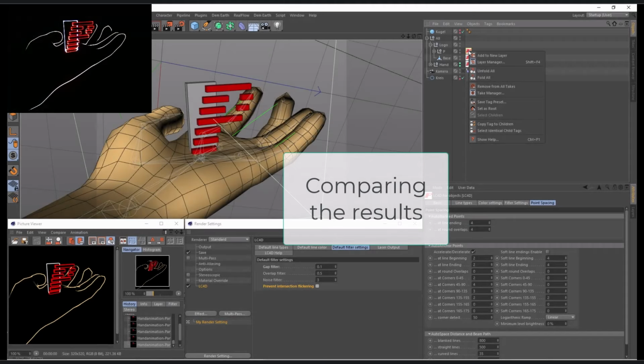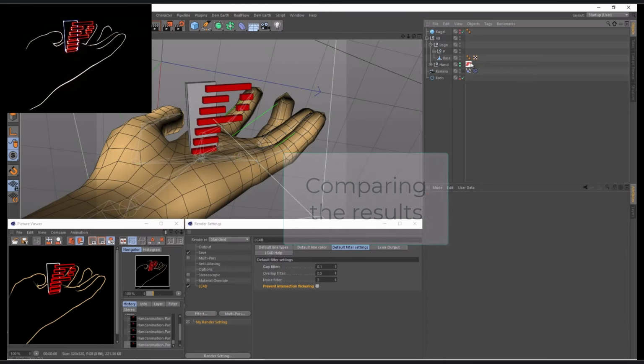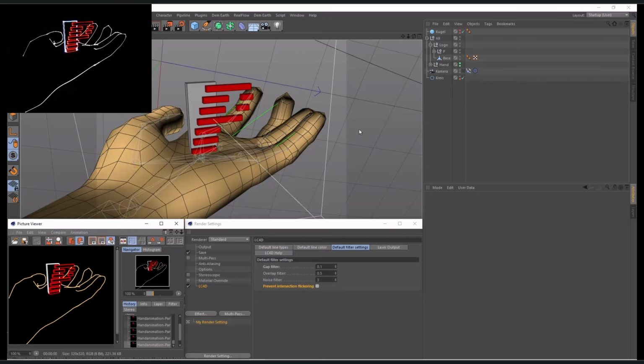After all this optimization and point filter settings, let me deactivate all filter settings just to compare the point density with and without all settings. And counting points in the output window shows an overall 1680 points, which of course is normally far too much for standard scanners. So I might even deactivate more filters here, but then the output quality will be even worse.